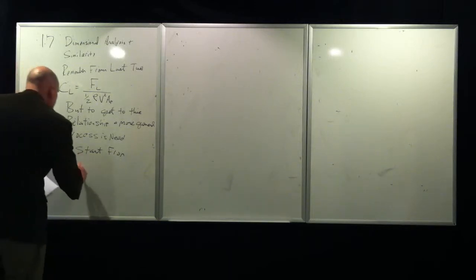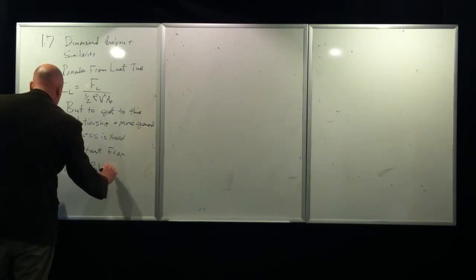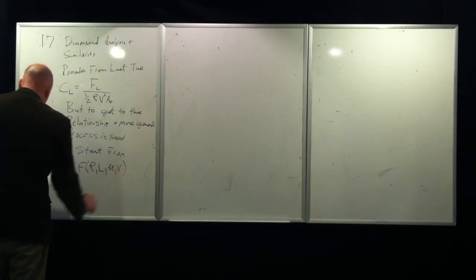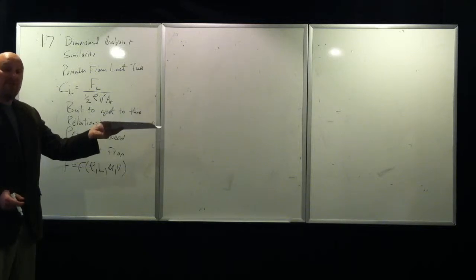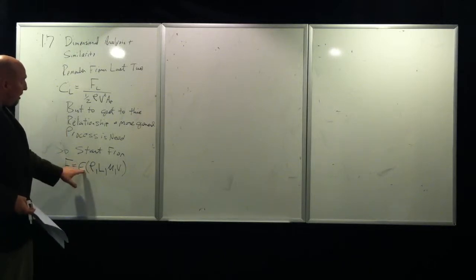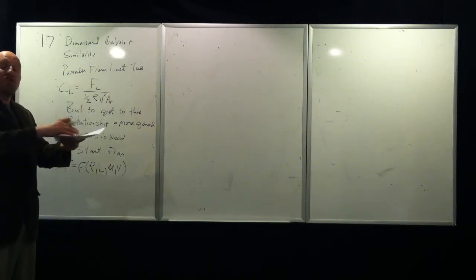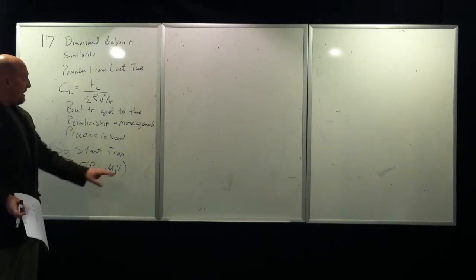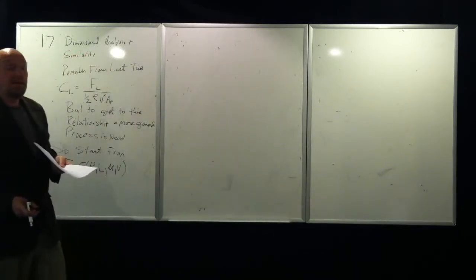Force is going to be represented as a function of the important parameters that are fundamentally different between any particular shape and any particular flow regime and that affect force: the density of the fluid, the length of your geometry, prototype or model, or the shape, the viscosity of the fluid, and the velocity at which the fluid or object is moving within the fluid.